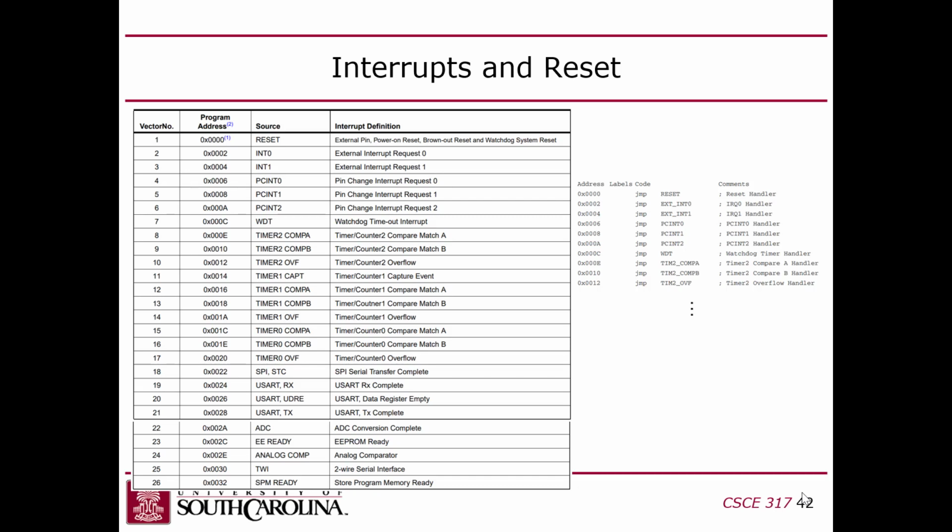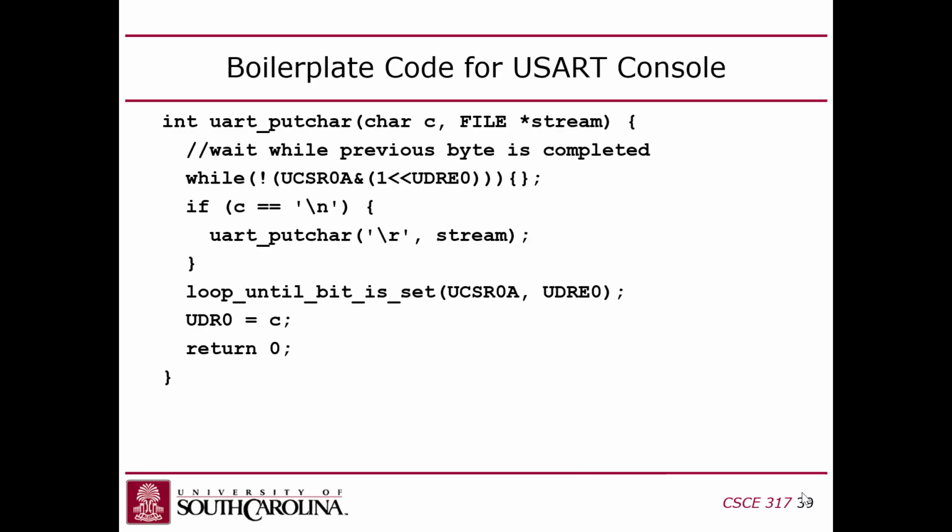There's 24 internal interrupts that are triggered by peripherals that are external to the processor but are still on the chip. One of which is the UART that I just got done talking about. Instead of doing what we've got in our code here, you see we've got this while loop here. This while loop spins. It just sits there and loops and doesn't do anything. It occupies the processor by essentially doing a loop that's just not doing anything until